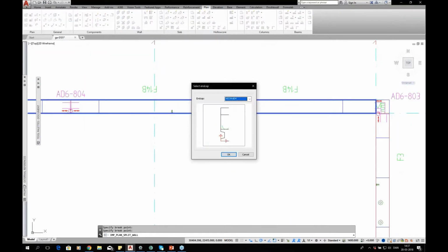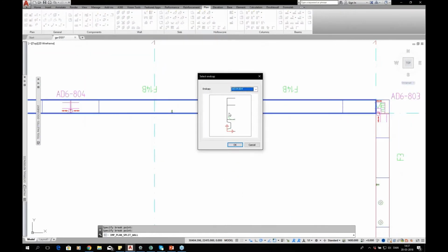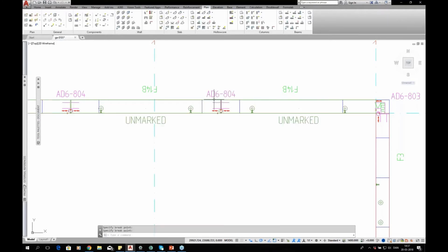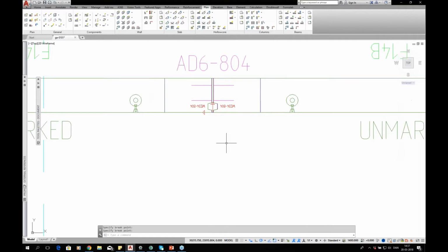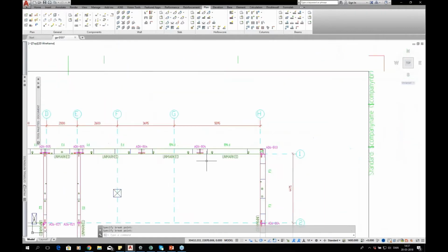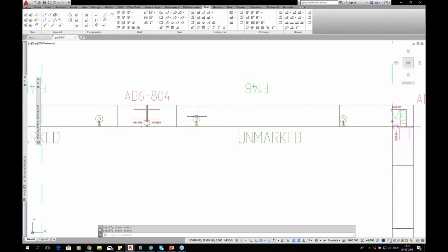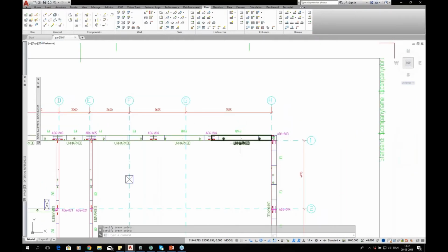chosen where to split them, I can decide which type of connection I want, an end cap we call it in Tekla. Now this one, 804 we call it, looks like one that's just fine for these walls and ones that look like the same that's been defined here. So this is what I'll use. So straight away now you'll be able to see that we actually have some lifters and inserts in these elements. If I hover my mouse over it, you can see element type sandwich wall. The mass is a little under 8 tons. And this element is 3.9 meters times 2.8 meters.